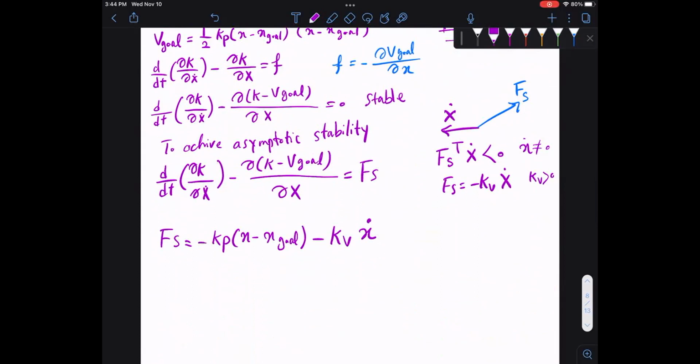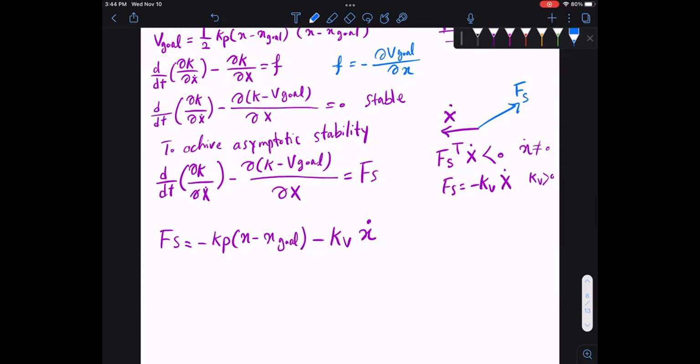If I apply this force, this fake artificial force that I created, to the dynamic of my system, which was mx double dot. So if you solve this for that prismatic, it is mx double dot. We can find it from Newton's law that I did. We can also find it from this. You will get mx double dot. So you basically have mx double dot equal to fs.